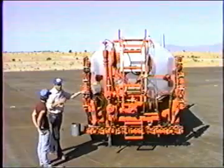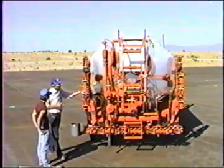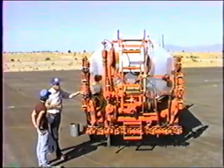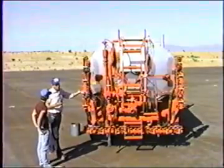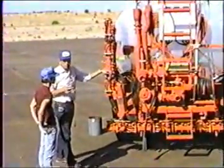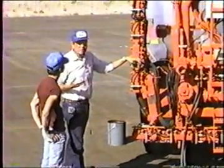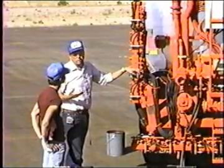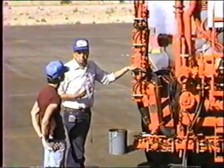We talk about application rate for asphalt distributors in a unit that's called gallons per square yard. And it's really always a part of a gallon per square yard. Common spread rates are anywhere from 5/100ths of a gallon to the square yard up through 5/10ths. Sometimes you might go as high as 6/10ths and 7/10ths. It's very rare to go over a gallon per square yard. That'll come up now and then, but it's a very rare situation.